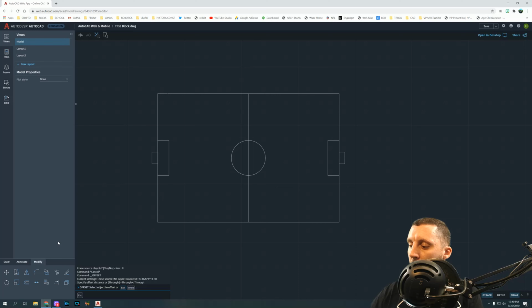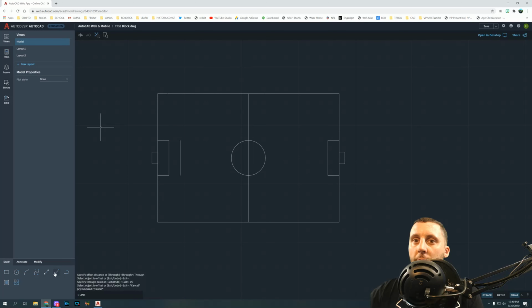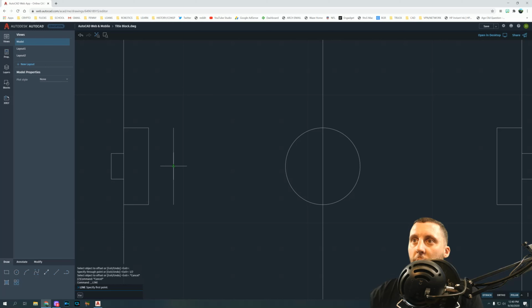You're going to go, oops, sorry, don't type your number yet. You're going to go from here and go to the right, 1/2 inch. I'm going to take a line, and this line can be any length, it doesn't matter. This is going to be a dummy line. A dummy line is basically a line that you're going to end up erasing later on. If I want the line to be 1/8, then I'm going to go 1/16 up.